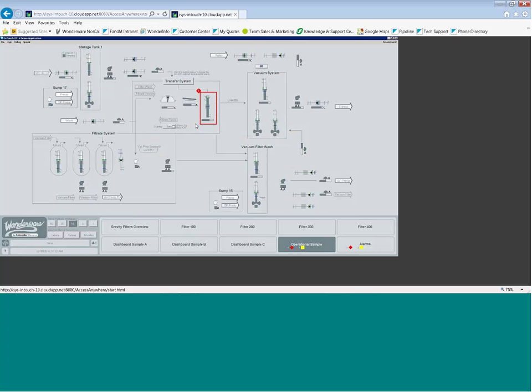It doesn't take months and years of training for an operator to know where to click and where to find problems. Using alarm borders and high-performance HMI concepts, it makes it very easy for anybody to walk up to a screen and see where there might be a situation they need to respond to.